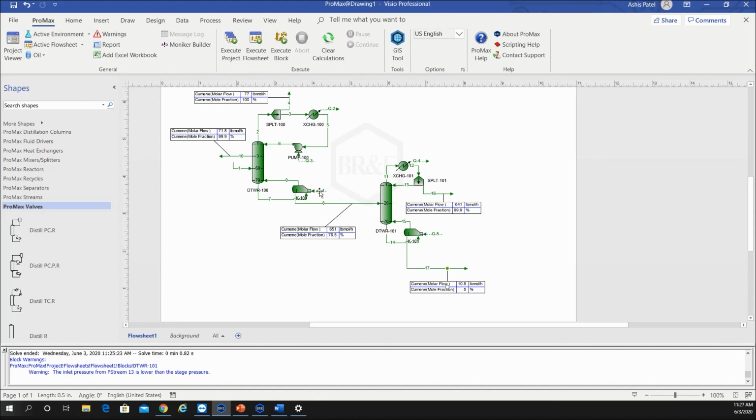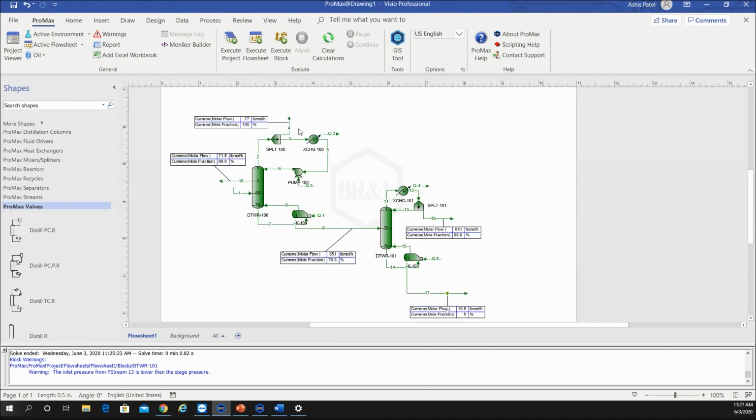And the same thing for the heat duty in the first column. We need to make sure that this is a feasible amount of heat duty. If we're thinking of increasing our flow rate or our recovery in stream 10, we need to boil up more cumene, which is going to take more heat. So we need to see if that's okay to do. And we need to see what impact reducing this purge on the top would have. Another place to look at your heat duty is going to be these condensers. We need to make sure that amount of cooling is okay and to make sure that the volume of liquid re-entering the column is going to be okay.